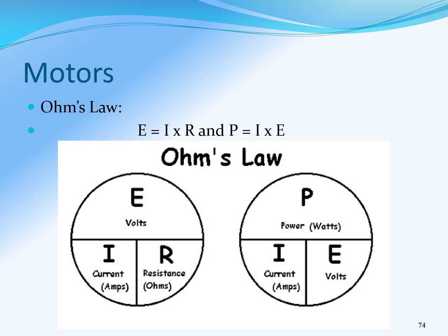I know some of you like the linear setup, so you can look at those formulas on the top of this image of Ohm's law and work your problems that way. But for those of you who like the pie charts, if you're working your way from the bottom to the top, you're going to multiply, and if you're working from the top down, you're going to divide.